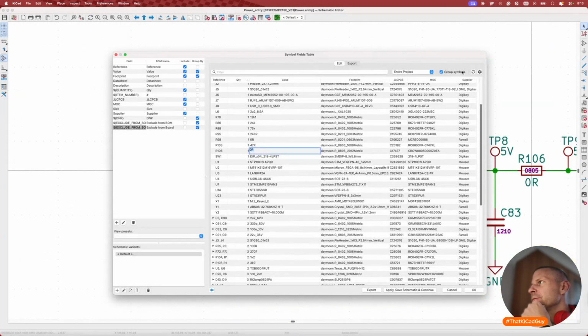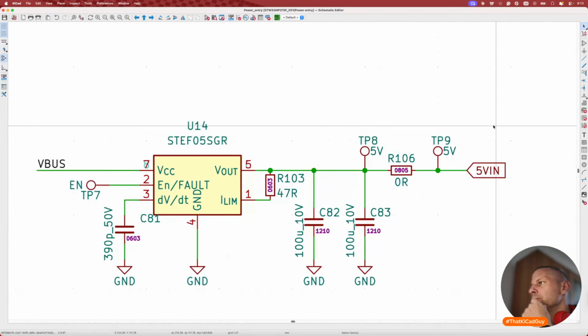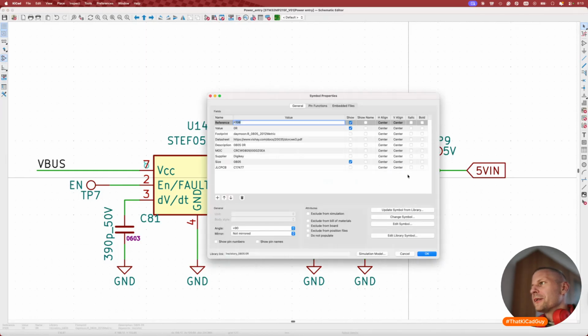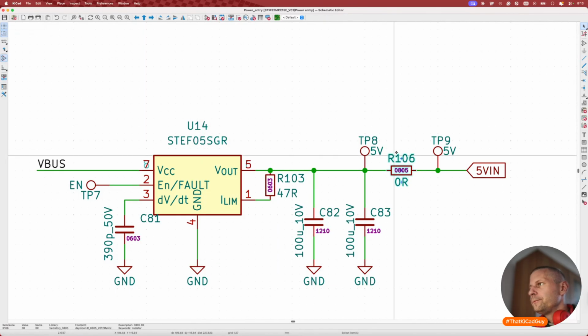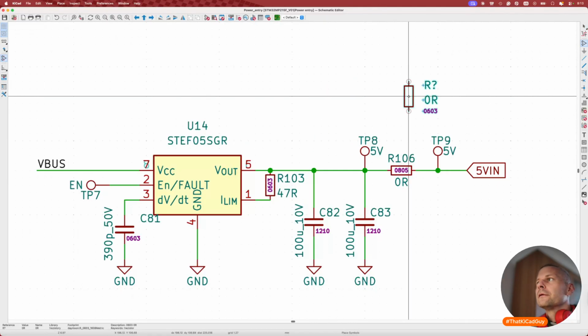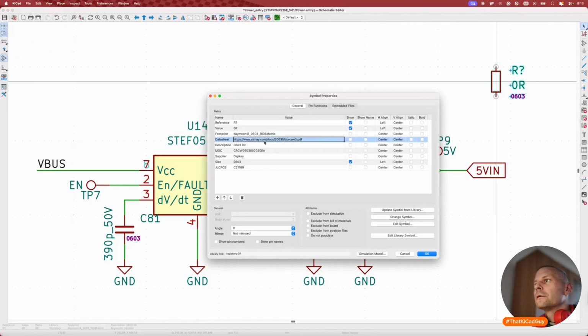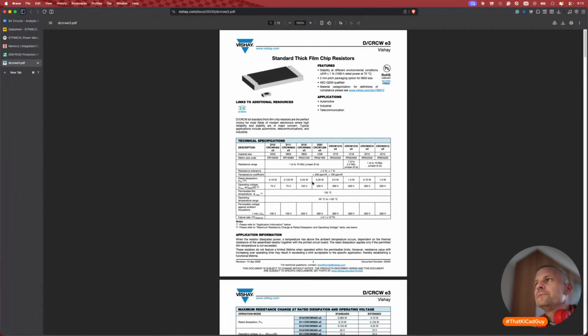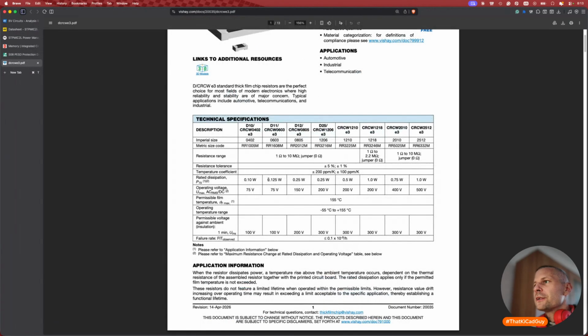And this one, I don't know what's the maximum current of the 0603. The dissipation is 0.125 W, which is funny because there is 0 ohm resistance. So I don't know what's the maximum current.